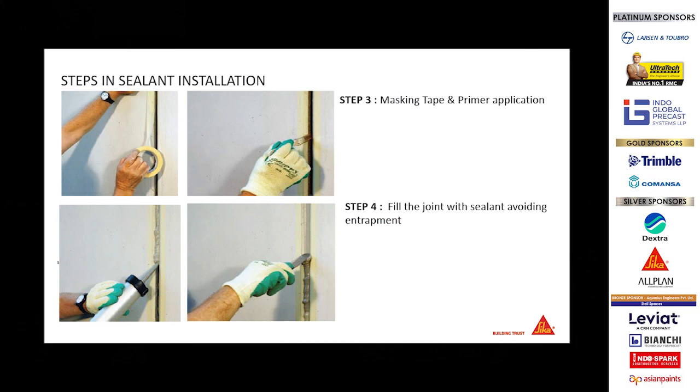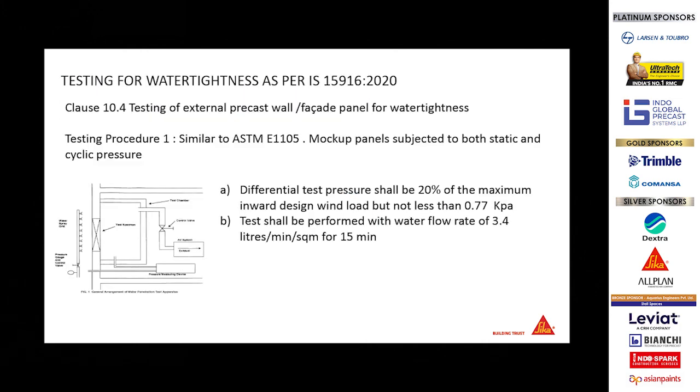And again, while applying a primer, which is again solvent based, you should wait for half an hour, or as specified by the manufacturer, for the solvent to evaporate, and then use a sealant.